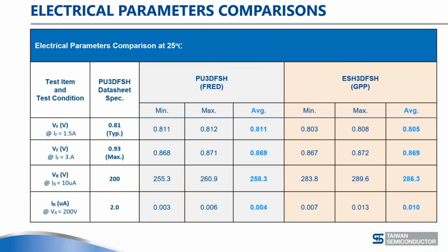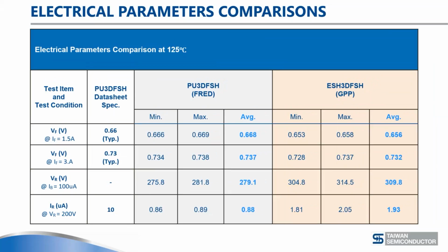There's no difference. If you go to the bottom line, we can say that it has a lower leakage current, but frankly speaking, 4 nanoamps is lower than 10 nanoamps, but it's really also peanuts. It's really not that much. So the data sheets of these devices are not that different, or the actual performance an engineer sees is not that different.